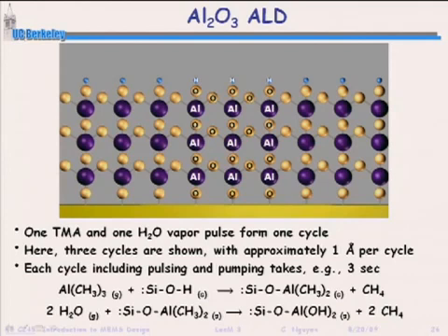They just sit there. You mean after you're done with ALD? You're done. Yeah, they just sit there. Everything has an OH group on it, usually, right? So water gets on everything, and it just sticks to that. And if you introduce more TMA, you can grow another monolayer above that. But at each step, you essentially end up with the topmost layer.